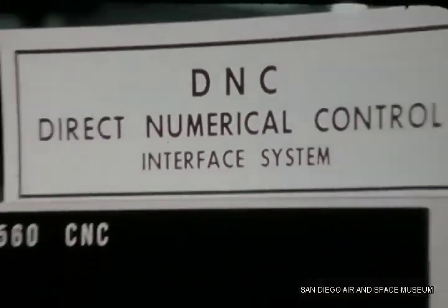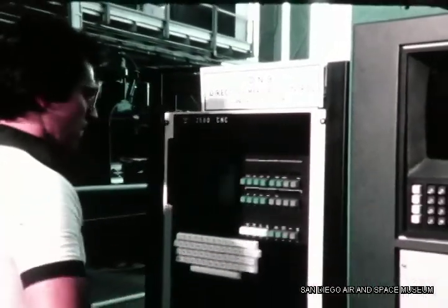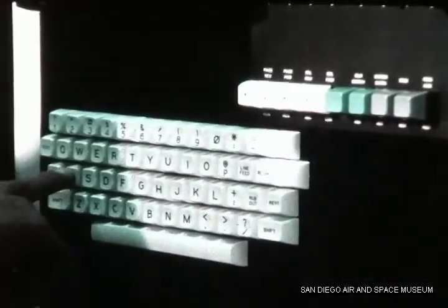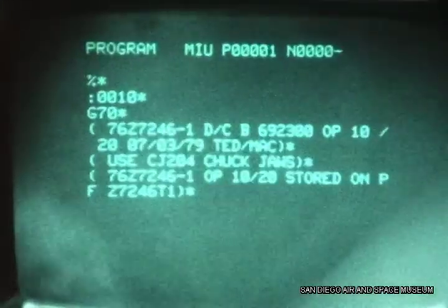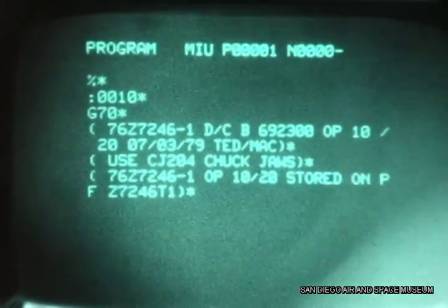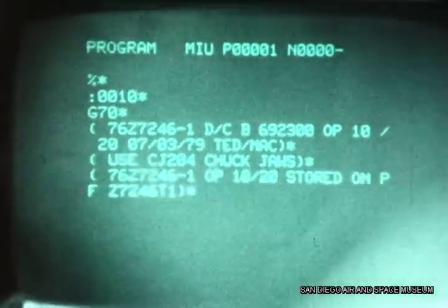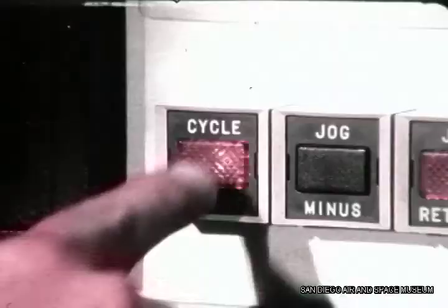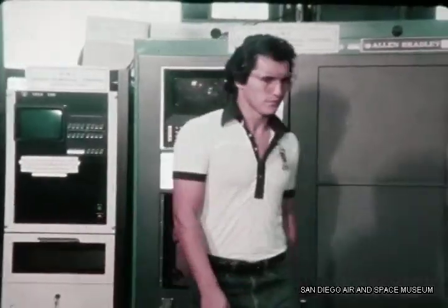With the DNC method, the machinist accesses a computer database directly by means of alphanumeric keys, and his display gives him instructions in plain English concerning the setup of his machine. After the setup, the machine is guided by part programs stored in the DNC disk device.